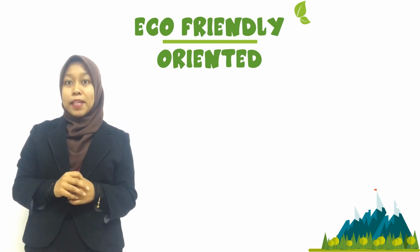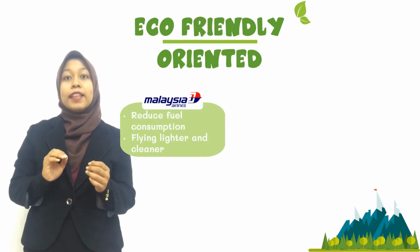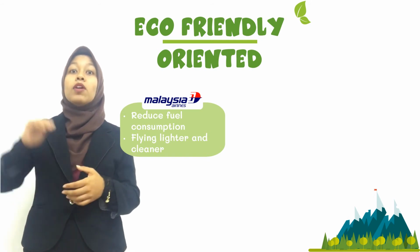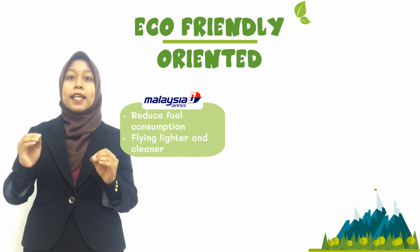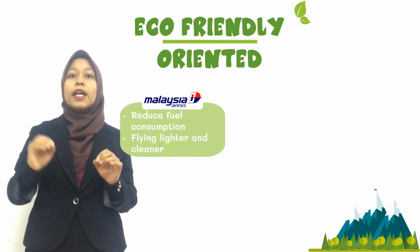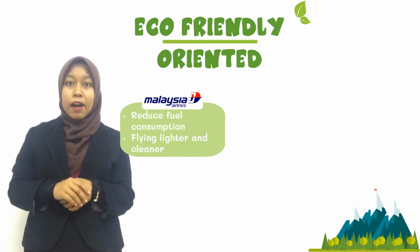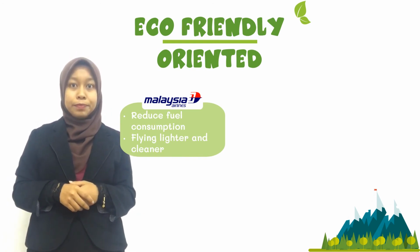The first company is Malaysia Airlines or MAS. Some initiatives that they did are reducing fuel consumption by flying more direct routes and at the most economical speed. They are also practicing a continuous descent approach, which is where their flight will have a constant angle descent to landing instead of doing a stair-step landing. They also fly lighter and cleaner aircraft to improve fuel efficiency. This somehow will reduce air pollution.